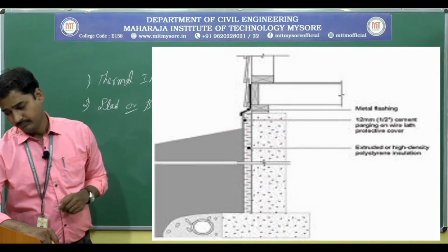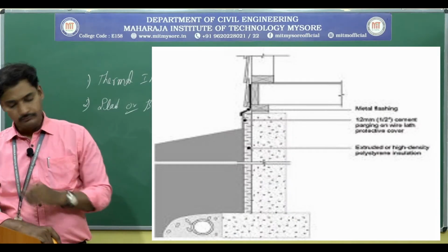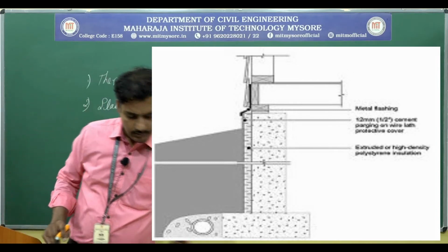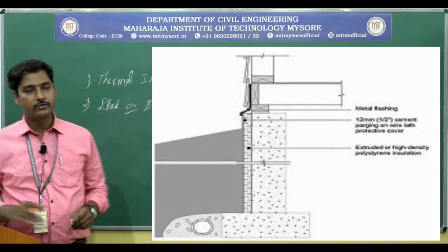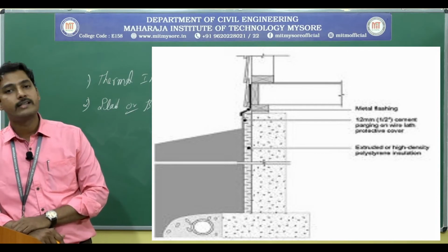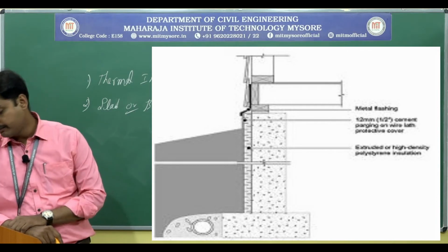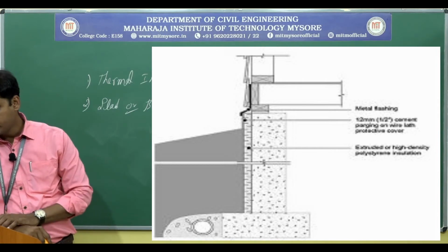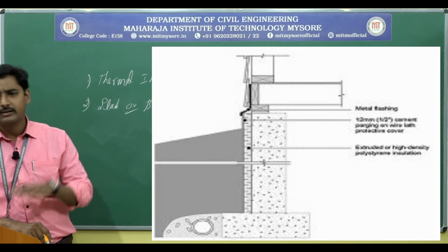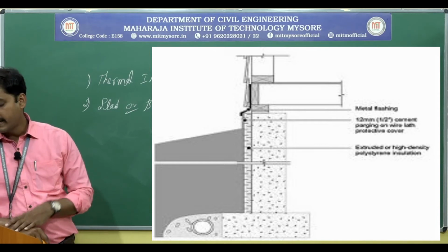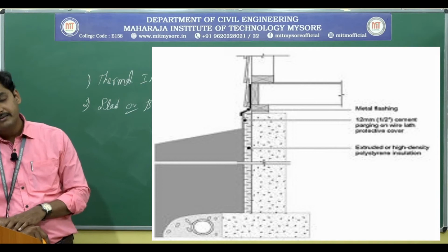Okay. So in this case we can even observe how the insulating materials are going to work. The second figure shows a solid ground floor insulation over the slabs. In this figure we can observe the bottommost part is the inner wall. On above we can have a hardcore, it might be your normal concrete, of minimum thickness. On above we can have a sand bed.